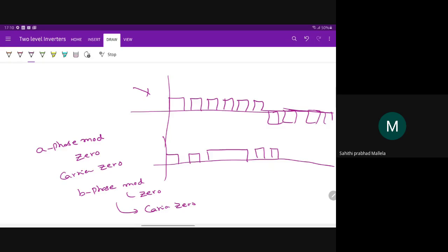That means the switching frequency of the inverter is reduced. All the harmonic spectrum is based on the switching frequency of the inverter. So the pulses are reduced, and therefore it will alter the harmonic spectrum. The resultant is lower order harmonics. Agree? Yes, sir.